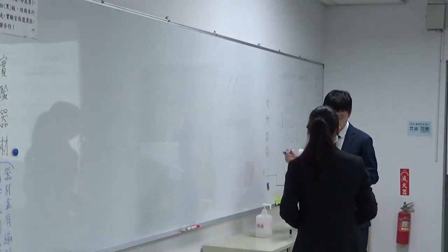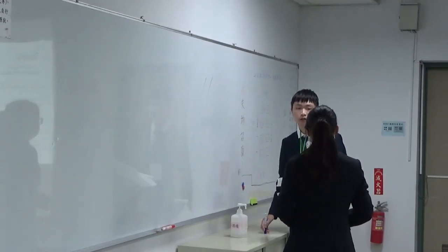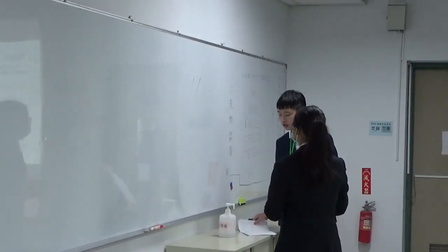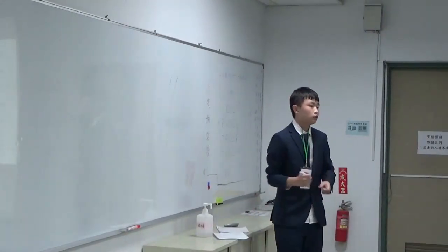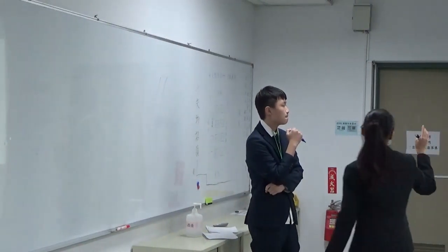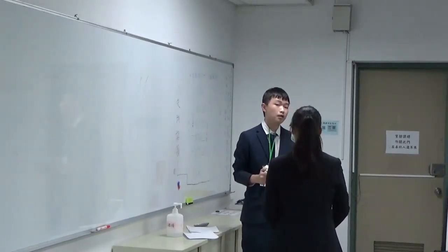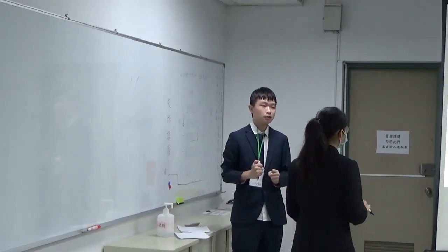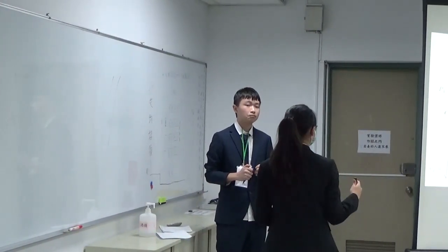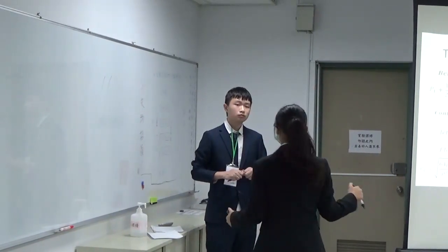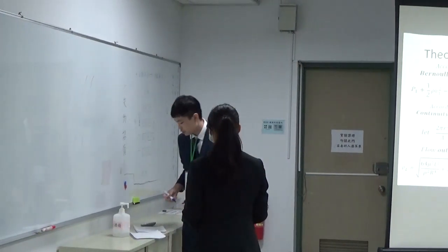The next question is, do you consider the viscosity of the water will clearly affect this phenomenon? We didn't do experiments, but I think if the viscosity is larger, the energy loss will be larger, so it will affect the phenomenon. Do you think in this condition the water's viscosity will be large or small? I think it will affect, but won't affect as much as some other parameters. Okay, I agree, because normally the viscosity of water is very small, so it can be ignored in this condition.